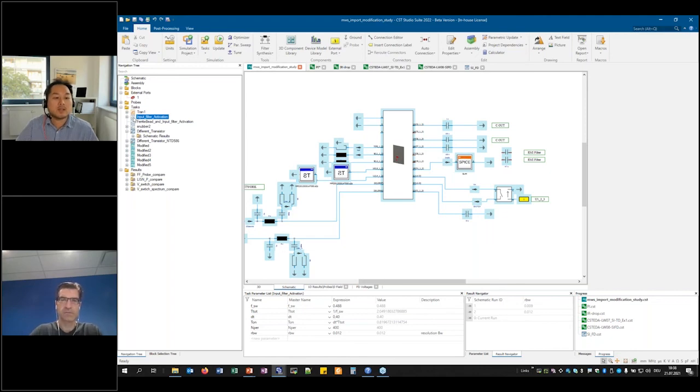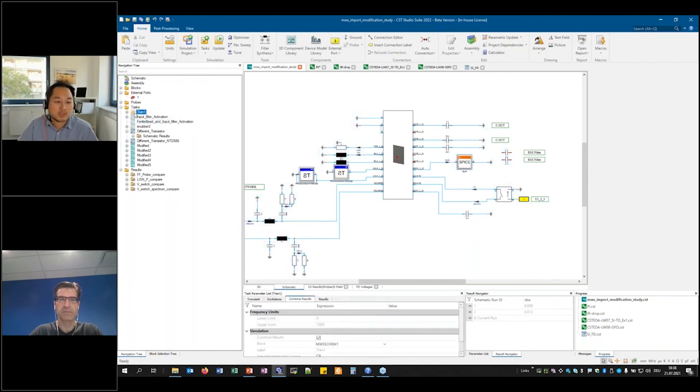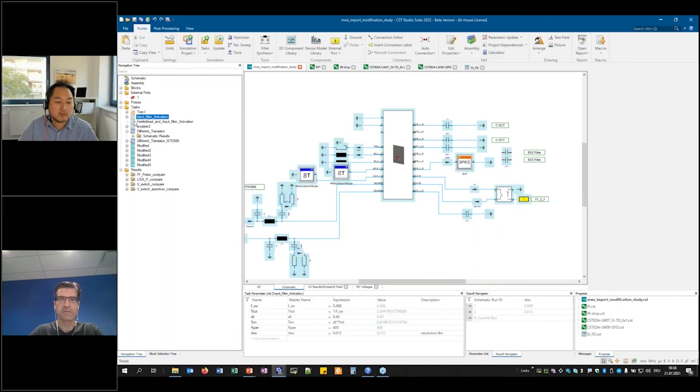And you can specify this subtask. And then, for example, a next subtask is you can say, okay, I would like to have a ferrite bead also implemented, and you would like to see the impact on the result. So the first task will be your reference, and then you can define several subtasks and compare the results later with the reference. You can also define subtasks, for example, a snubber. What are the results if I define a snubber? Or you can also define what if a different transistor is used. For example, I use a P MOSFET, or I am using an N MOSFET, and so on.